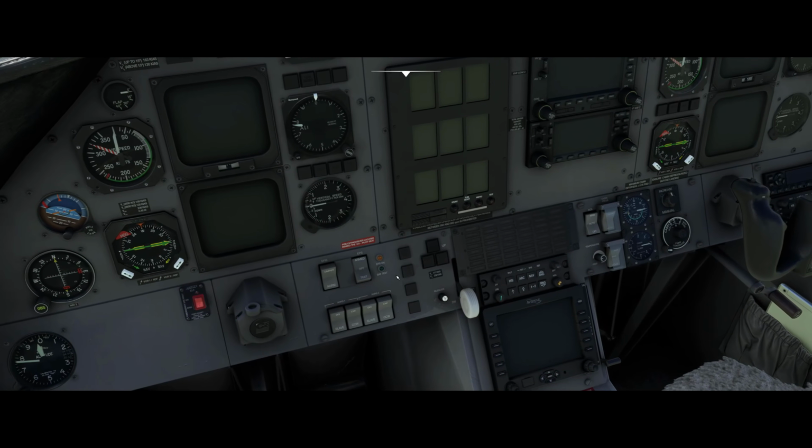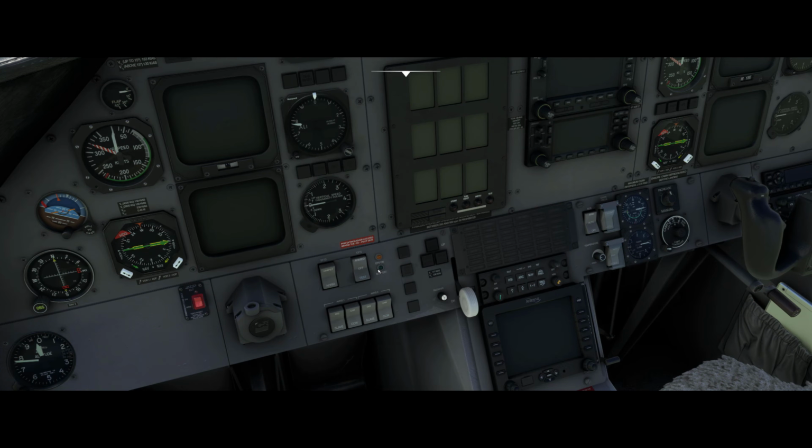The EPS, this switch would normally be set to off once we got in the airplane. Now if this were actually unarmed and this light was out, that would mean that we had a dead battery, which would be a no-go. That would be a no-fly scenario, so that would not be good. So I've noticed in the sim when you get in they have this set to armed, which is not how it would be in the real airplane. So that would normally be set to off.